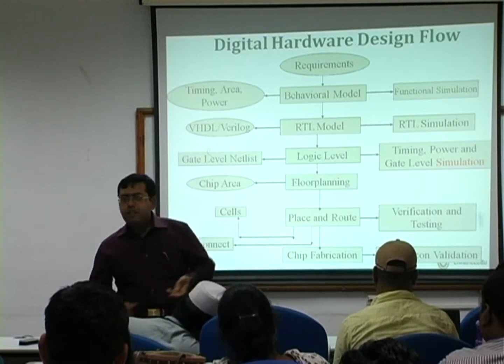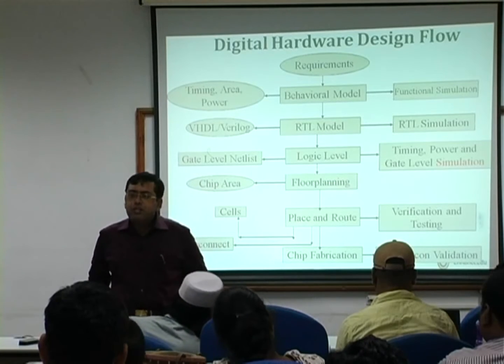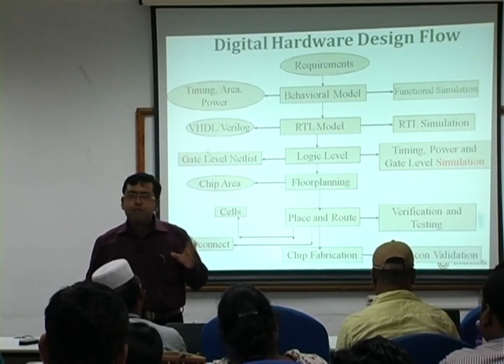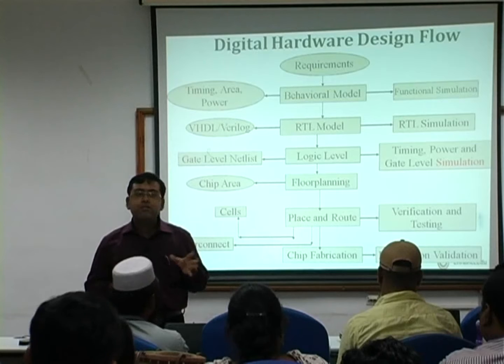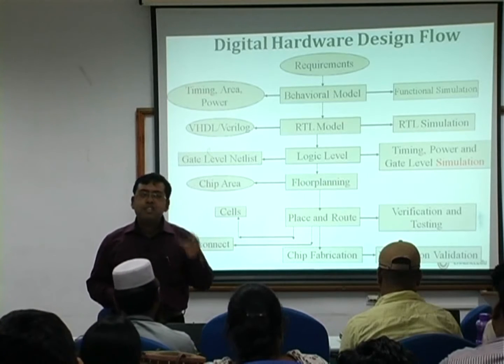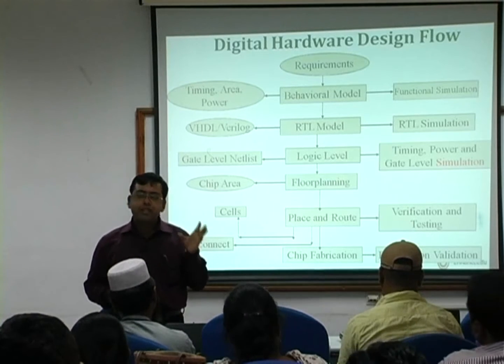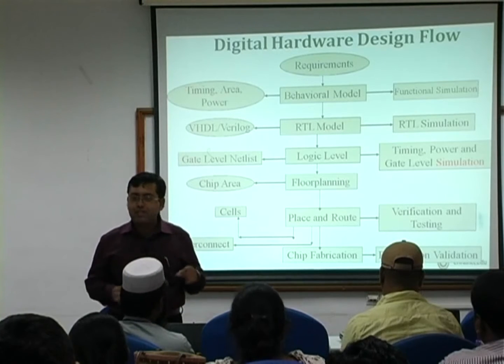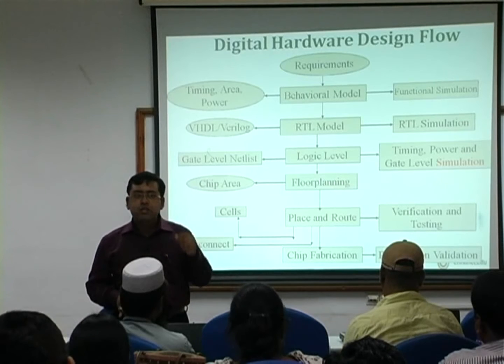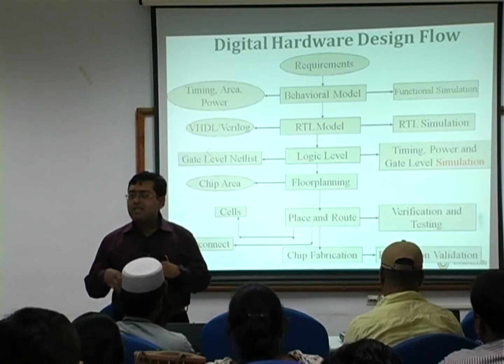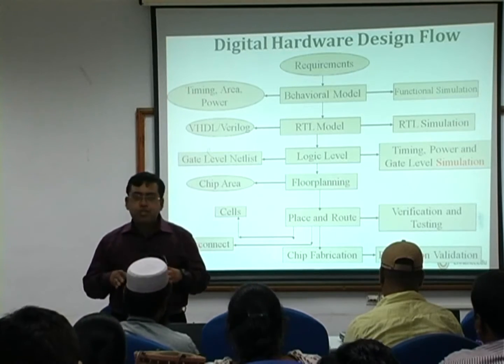Okay. Now after the layout is finalized, one of the important tasks that you should do is a schematic versus layout verification. What schematic you have finalized gives you a certain set of results. You should see whether after generating the layout you are getting approximately the same set of results or not.